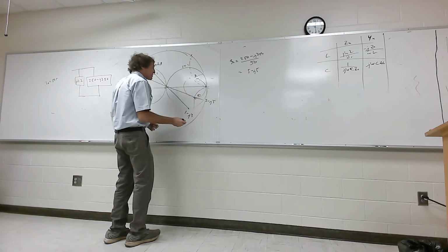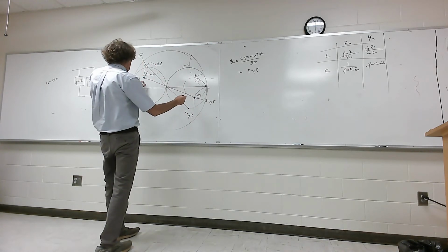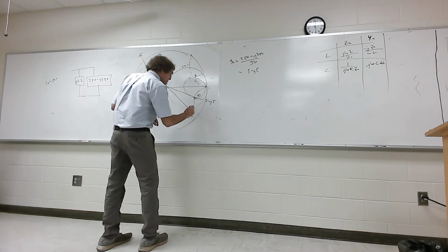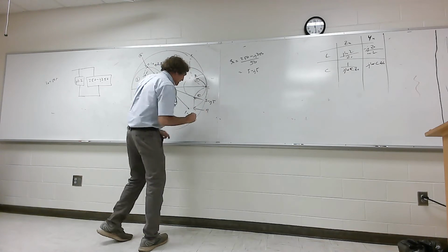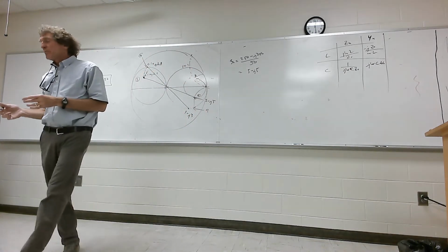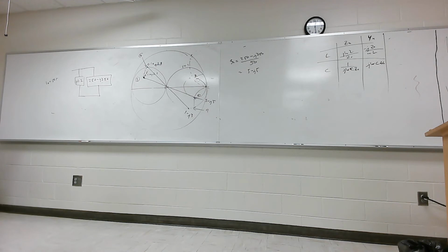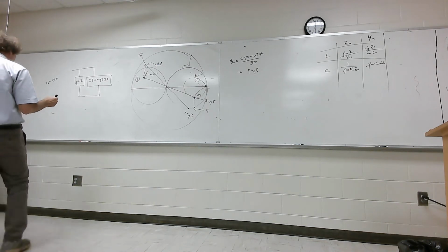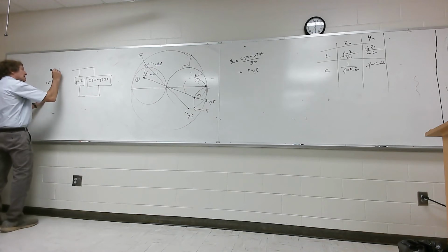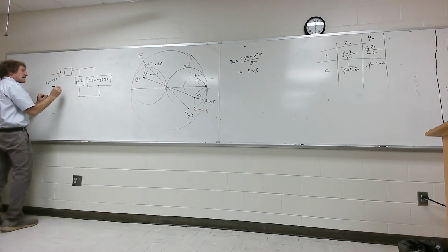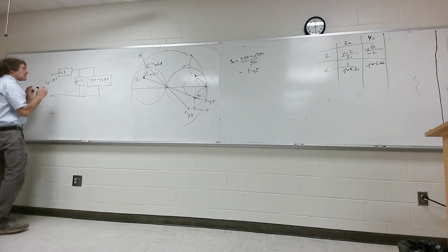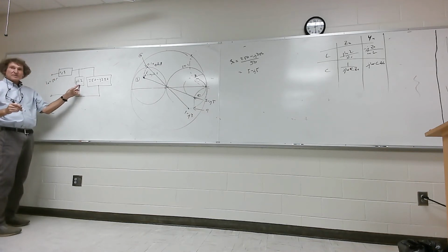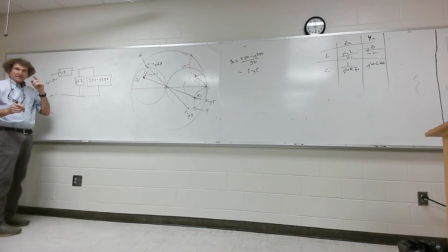So now we're here. We started here, 1, this is 0.2, that's 0.3, this is 0.4. Now we've got minus J3, we want to get rid of that, we add plus J3 in series. This is the impedance domain. So now here, I'm just going to add plus J3. And now, from that point on, I'm impedance matched. This will be a capacitor, this will be an inductor. We're going to get the values in a second.